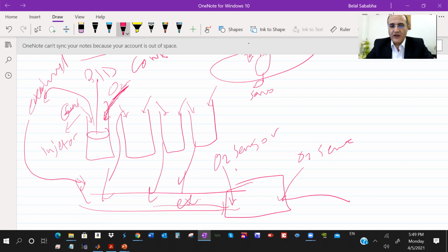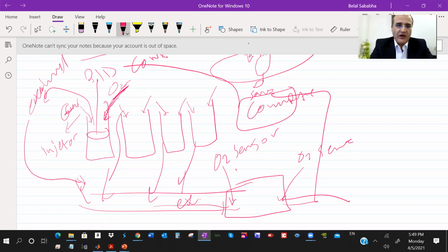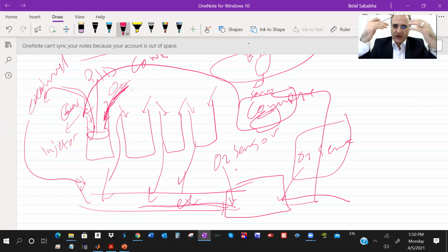in the exhaust, and this will go to a computer, to adjust if you need to increase or decrease the amount of gas that should be injected based on the oxygen you allowed to get in. So you allow more oxygen, there should be a controller, for example, in the computer. You allow more oxygen to come in, then you should inject more gas to burn it, right? If your exhaust has more oxygen than is acceptable, the ratio of O2 to fuel, they call it lambda.